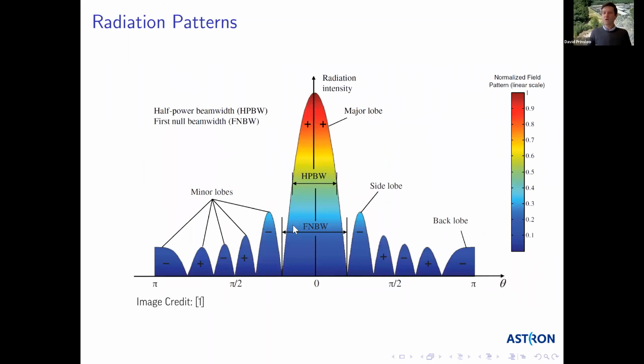And lastly, as I mentioned, you have the Cartesian graph as well. And here you've got the angles of theta, which here is scanned from the z-axis downwards. We have on the x-axis, so this is our theta angle, for example. And you can read exactly the same quantities again from this graph. So you've got your main lobe, your side lobe levels, your half power beam width, etc.